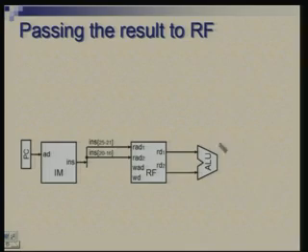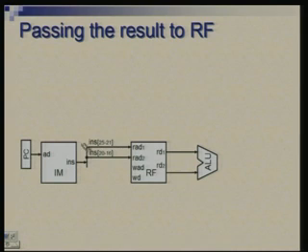At the moment I am not worrying about how to control the ALU to do the right function. We are looking at those 5 instructions together, and the ALU would need to be told which of these instructions it is. So, when we talk of control, we will look at bits 26 to 31, the opcode field, and bits 0 to 5, the function field. We look at those fields and then pass on some signals to the ALU, so that it does the right operation.